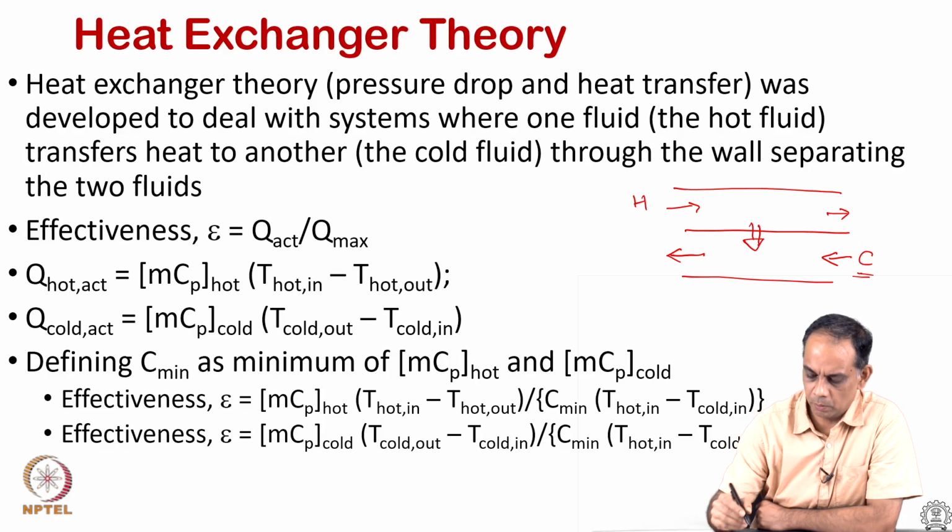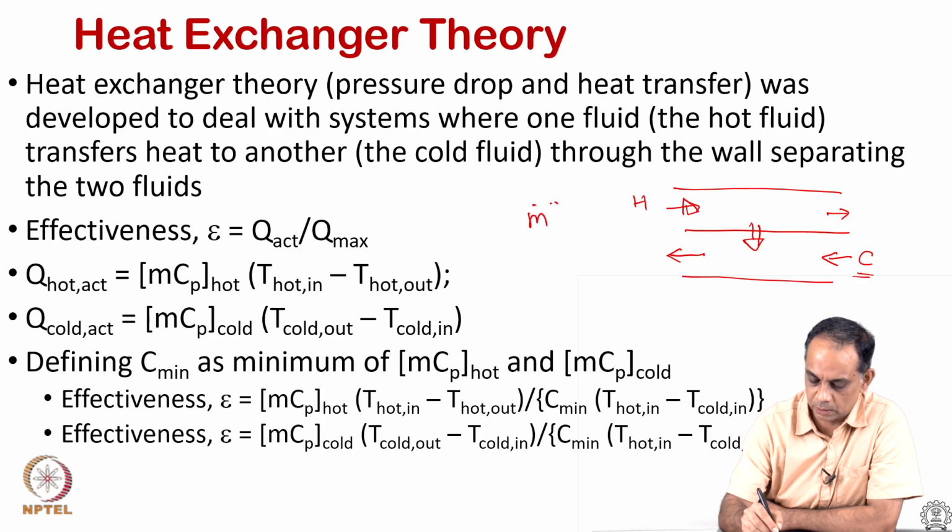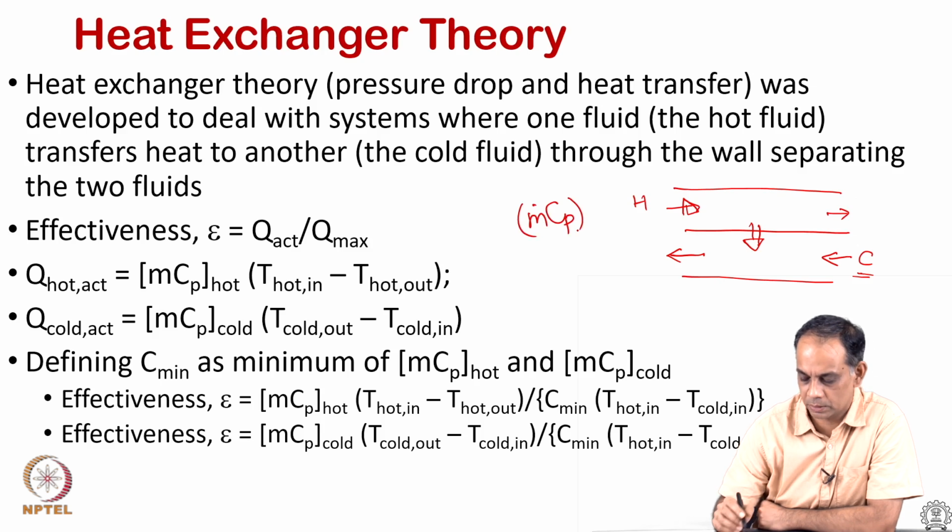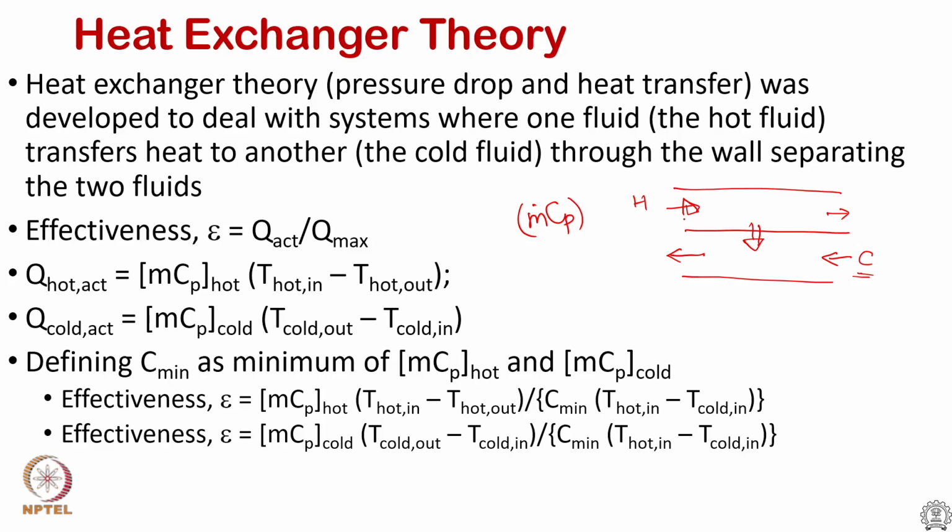But one main thing is that the heat exchanger emphasizes the capacitance of the flow rates, that is m dot Cp is the critical parameter, or the capacitance ratio is the one that determines the maximum heat transfer rate one can achieve, which will be based on the minimum capacitance of the system. In this case, where we have a solid exchanging heat, one can understand the system to be of this nature,